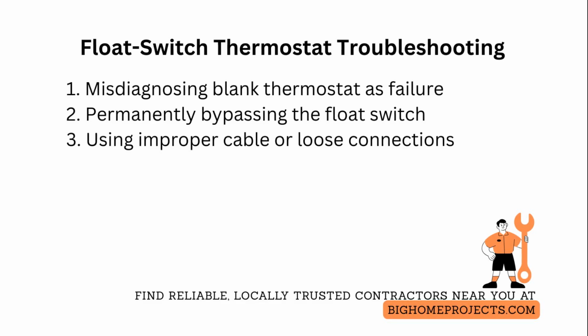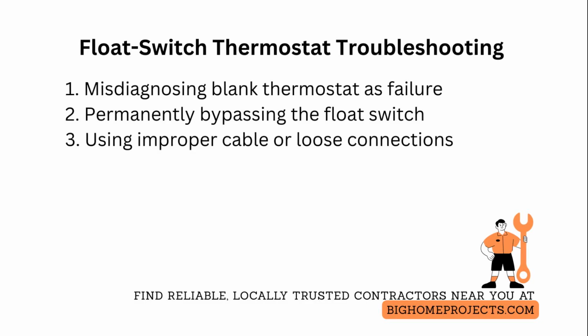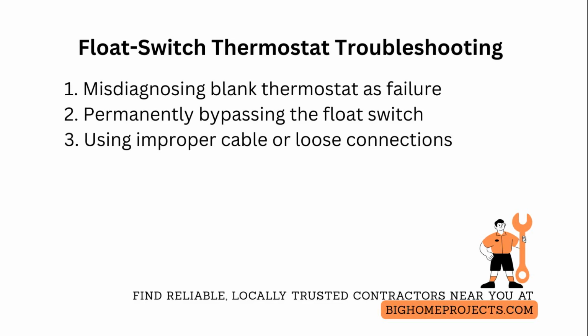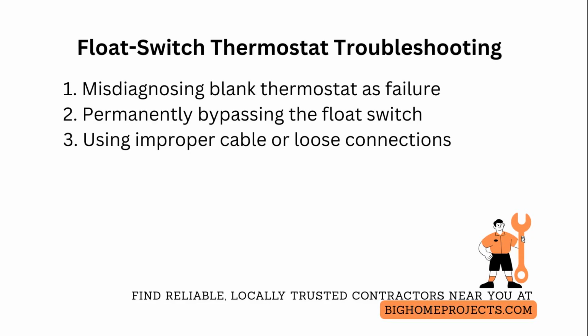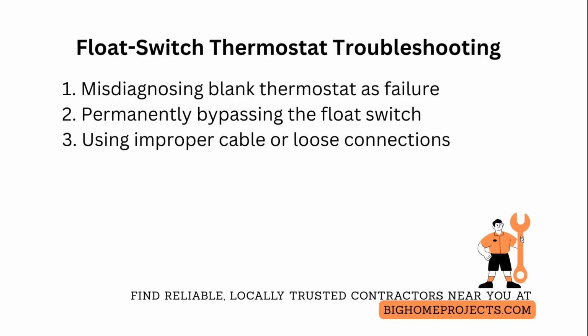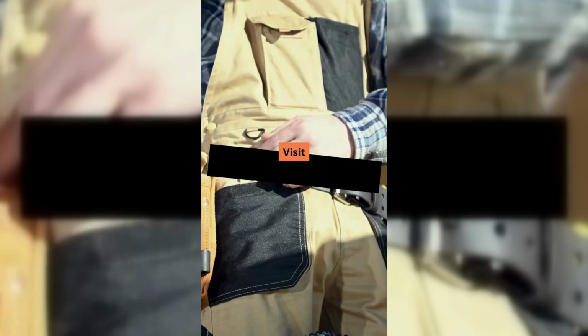The third frequent issue is poor cable choices or loose connections in the equipment cabinet that cause intermittent thermostat blanks. Remedy that by using proper stranded thermostat cable, secure screw terminals, and strain relief, and label all conductors so future troubleshooting is straightforward.